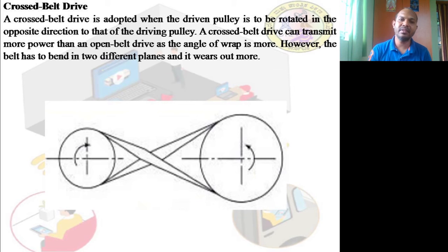Basically, belt friction depends upon the friction at which it operates, but excessive friction wastes energy and also rapidly wears out the belt with higher temperatures. Factors that affect belt friction include the belt tension and contact angle. Because the contact angle and the belt friction tension will be more here in the cross belt, cross belts will wear out much faster compared to open belt drives.